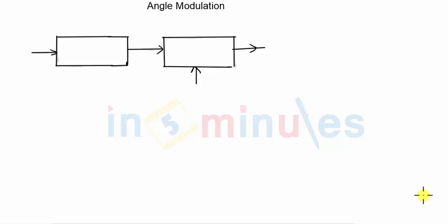In the previous video clips, we have defined FM and PM signals mathematically. We had also discussed two ways to generate FM and PM signals. For example, if I want to generate FM signal, then I can change the frequency of the carrier signal directly in proportion to the modulating signal amplitude, or I can also change the phase of the signal in proportion to the integration of the modulating signal. Both these approaches will ultimately result in frequency modulation.